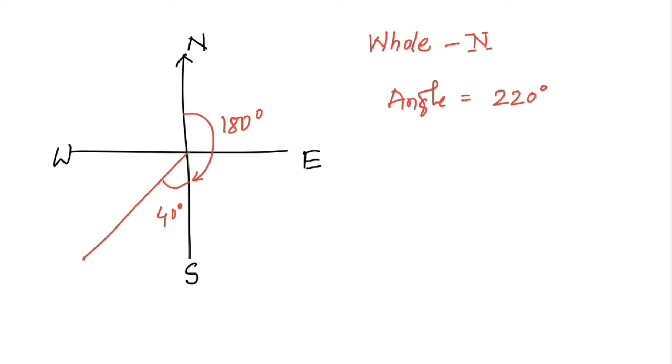Whereas when it comes to the quadrantal or reduced bearing system, we'll be using north and south as references, whereas when you draw a line in between anywhere, or the angle to be measured for a respective line, in that case the angles are measured with respect to north, either north or south. Okay, later we'll be writing in this manner.